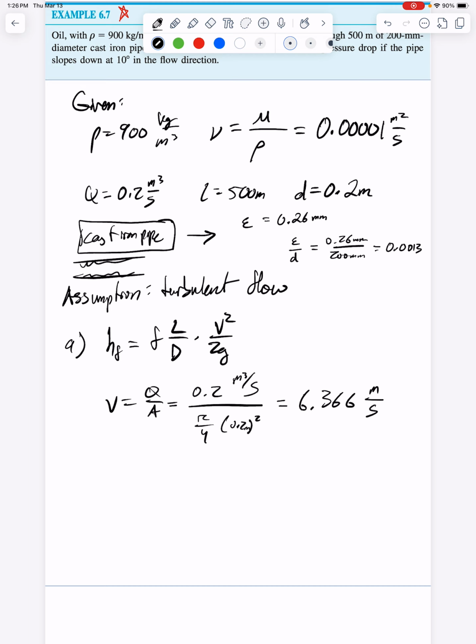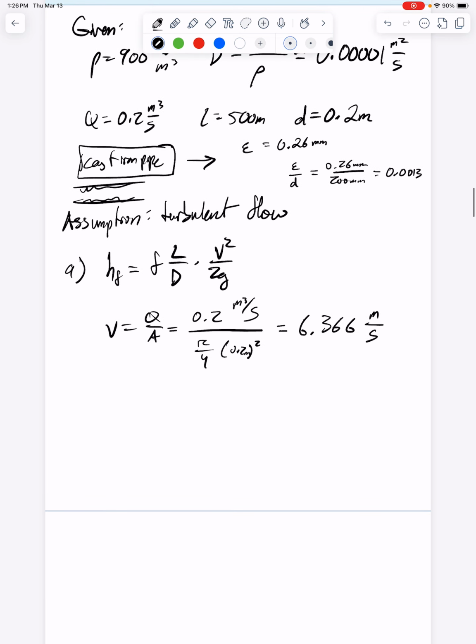Anyways, so that's our first pipe group. Second pipe group, flow characteristics. I'm referring to Reynolds number. That's what I'm talking about. That tells me my flow characteristics. So Reynolds number for pipe, Re_D, is rho V D over mu. But in our expression, it'll just be V D over nu.